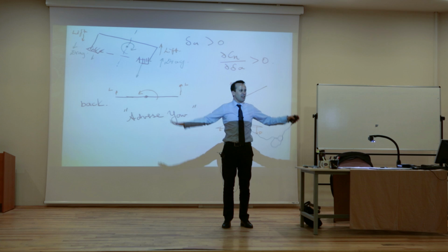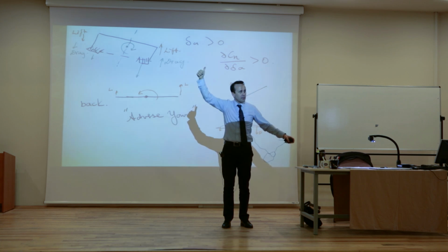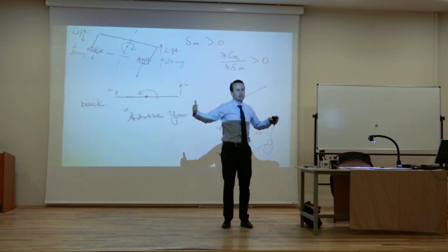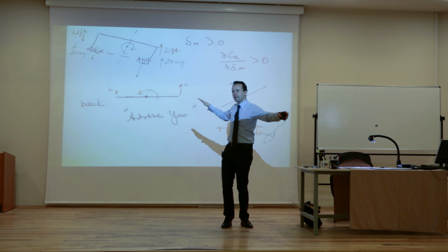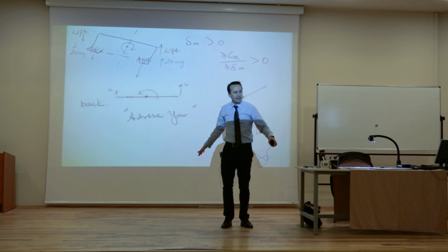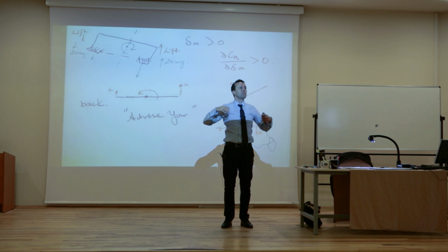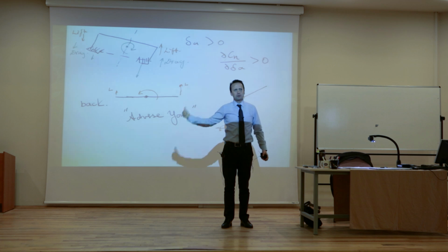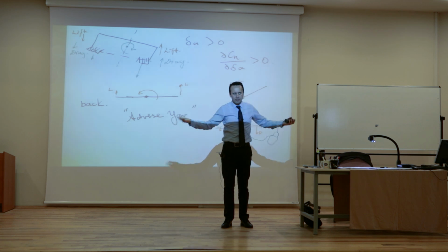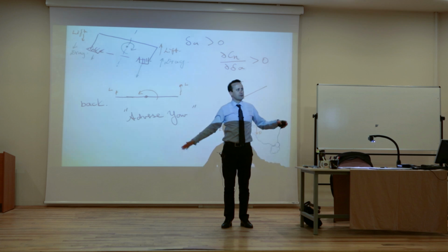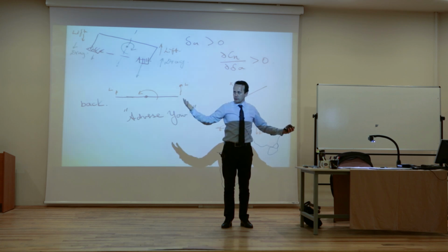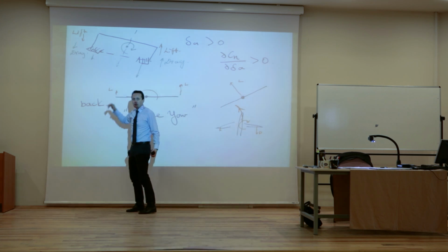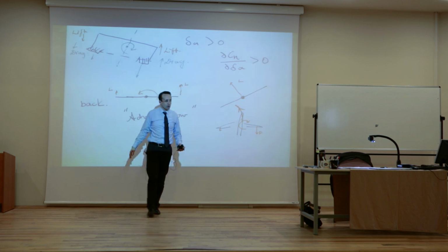But let's say you make a fast turn, meaning the lift on this side is really big, the lift here is really small, and the difference is large, so there's a large difference in the drag, and you really have that adverse yaw. That happens if you make a fast turn with big wings. Big wings means a big moment arm, lots of lift difference. There will be a lot of drag difference: big wings, big forces, fast turns. The difference in lift is large, therefore the difference in drag is large, and you have that large adverse yaw.